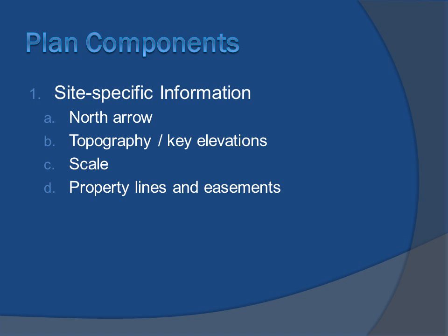Sometimes you'll see 1 inch equals 30 on the engineer. I've seen that, yeah. That's getting a little small. But property lines and easements, we've learned how to do that with our protractors. When we get a bearing of the property line, from north in the easterly direction, 30 degrees, we can figure that out and we can draw that property line.